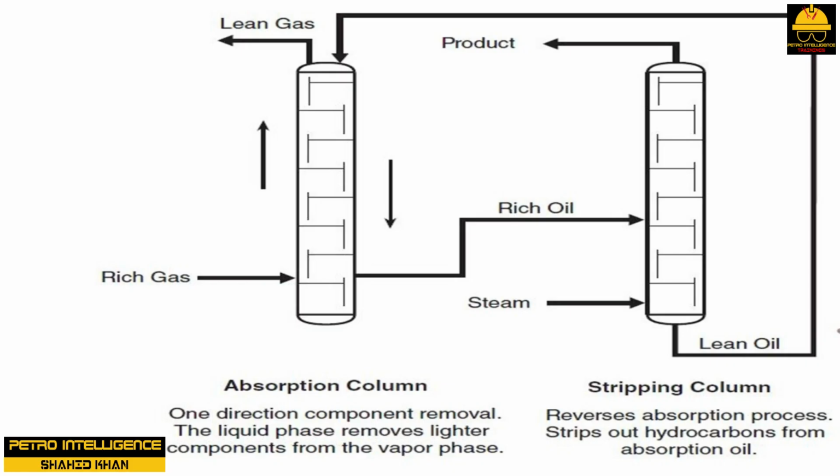Absorption columns. An absorption column is a device used to remove selected components from a gas stream by contacting it with a gas or liquid. Absorption can roughly be compared to fractionation. A typical gas absorber is a plate or packed distillation column that provides intimate contact between raw natural gas and an absorption medium. Absorption columns work differently than typical fractionators because during the process the vapor and liquid do not vaporize to any degree. Product exchange takes place in one direction, vapor phase to liquid phase. The absorption oil gently tugs the pentanes, butanes, and so on out of the vapor.